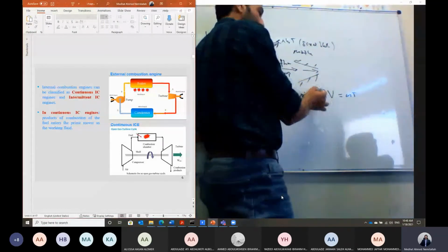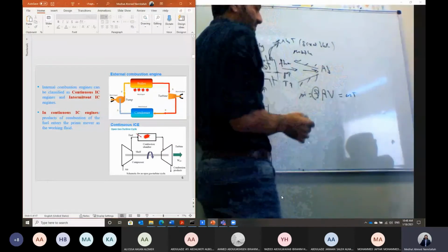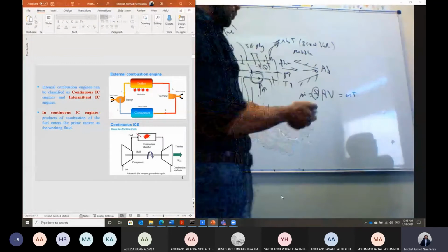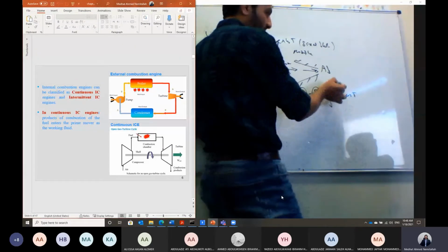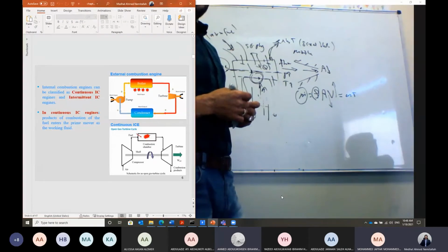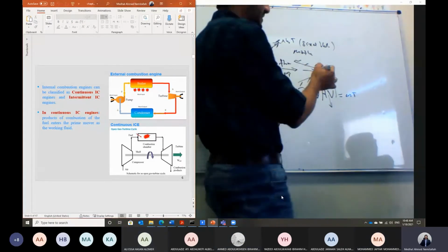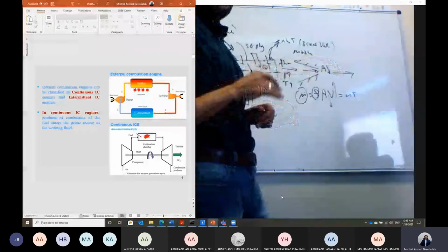And usually we don't have a change in density. So what will happen to the flow, Shabab, when the area is reduced in the flow direction? When the area is reduced at fixed mass flow rate, what will happen to the velocity? Velocity will be increased in this case. So we'll have a jet. The flow will create a jet of high velocity.